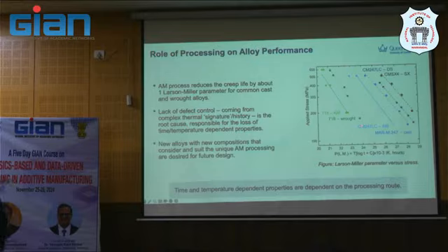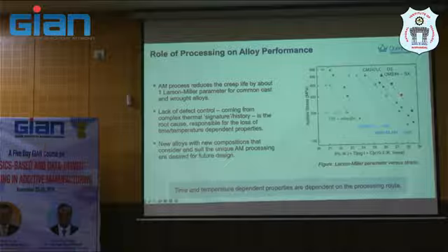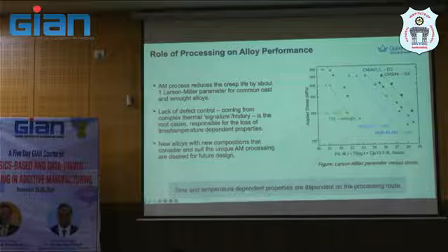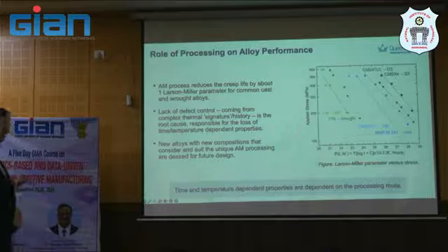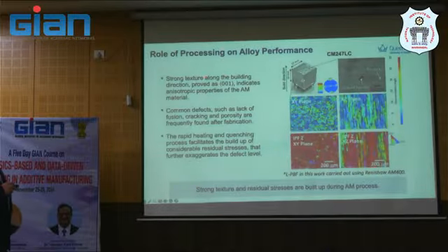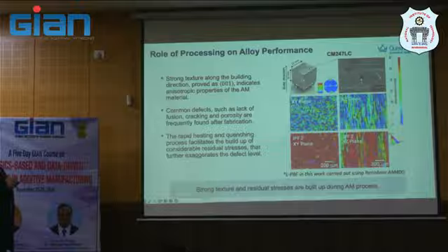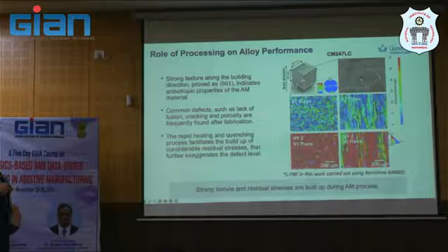The life of the material after printing is as-printed, machine-printed sample condition, so there will be some difference. Another thing is the role of processing in alloy performance. As you know, the material is very heavily textured, based on observations everyone knows. Properties are not isotropic, and there are some common defects. At that time we did not investigate this very much. Lack of fusion, cracking, or porosity are usually found in this kind of printing process.